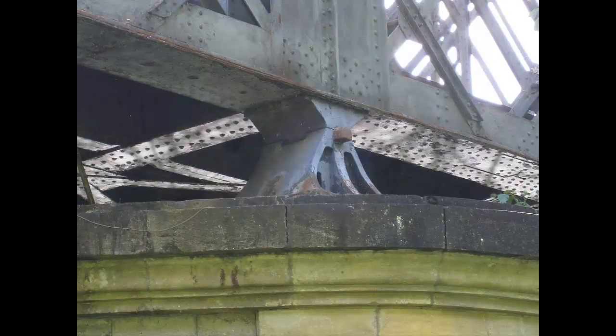What is the advantage of pin joints? Well, the pin allows adjacent members to freely rotate so that no bending is applied by the joint. But the pin still holds the members together so there can't be any relative translation.